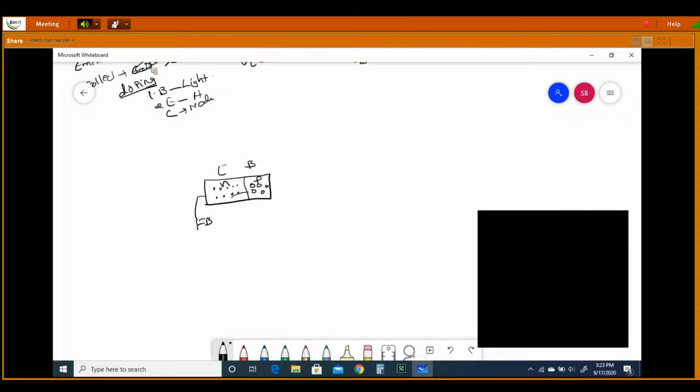These electrons came to the P region and they will become minority carriers, because in the P region, electrons are the minority charge carriers. That's why the concentration of charge is very high in the emitter, because the width of the emitter is very high compared to the base. All the majority charge carriers come to the P region and recombine with some of the holes in the P region. I am assuming 10% of the electrons recombine with the holes.